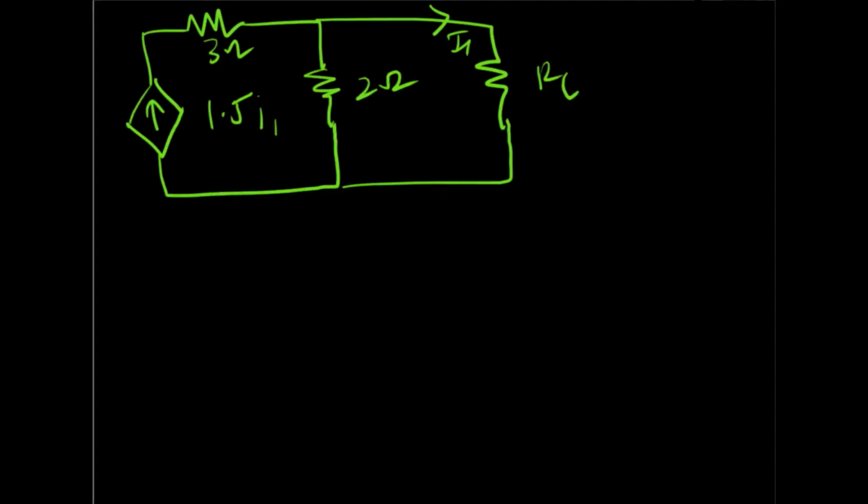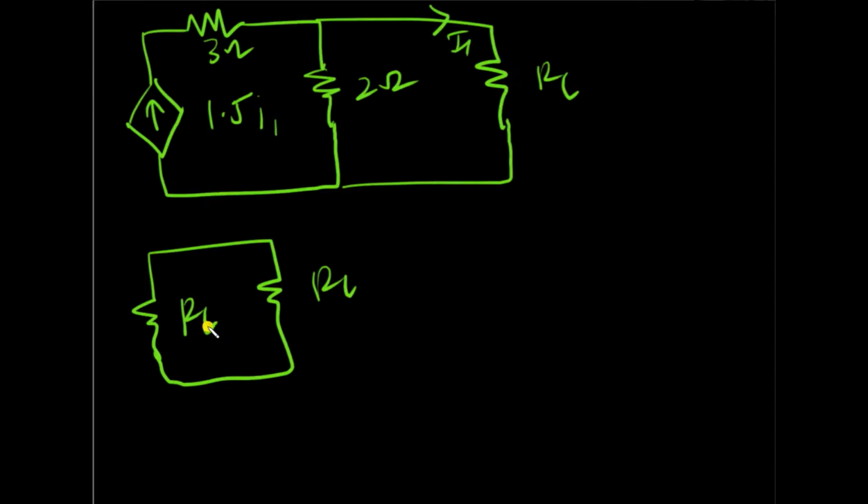So imagine you have this circuit and you need to find the Thevenin equivalent. One thing to clearly observe is that there are no independent sources here. So there would be no current or voltage through this circuit. So the Thevenin equivalent would look something like this, just a resistor, our R Thevenin. But how do you find R Thevenin?